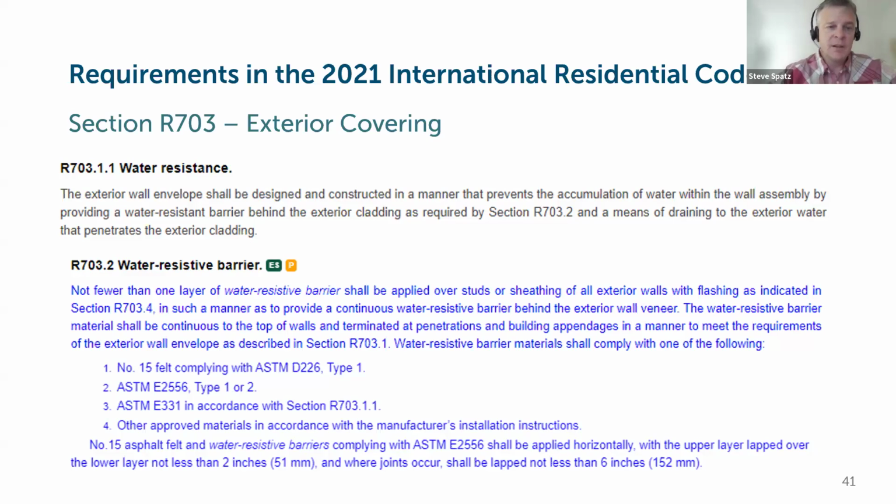So in context, the state of Vermont has not adopted the International Residential Code, but there is context there to be aware of and sections within RBES that reference sections of the IRC. Specifically to what we're talking about here right now are the sections of the IRC that define the criteria for exterior weather-resistant barriers, what are considered approved WRBs, and testing standards for manufacturers to meet if they are designing WRBs for use that are code compliant.